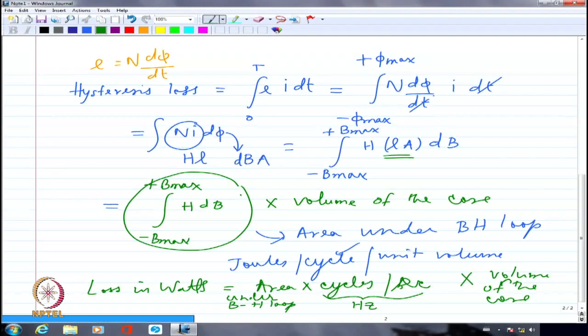Then all of them would have lost their domains already because you have powdered them. So they would not really have the hysteresis property much. Invariably, when we use a high frequency transformer, the core will be made of amorphous iron or powdered iron material. Then you essentially lose out on the hysteresis property, so there will not be much hysteresis loss to speak of.